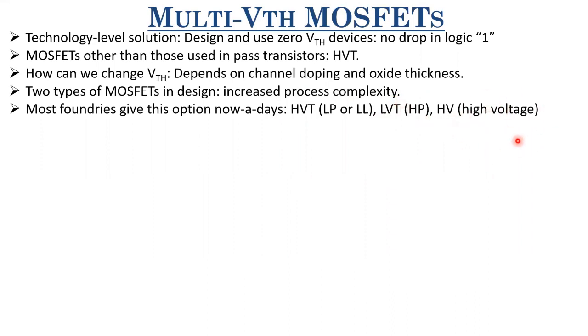And again, there would be some circuits where you need to sustain high voltages. For instance, the NAND flash or the flash memory in your mobile phones, the controller there, or the decoders, column decoders, and so on, use high voltage transistors because these flash devices need a programming voltage in excess of 10 volts. So in your mobile phone itself, for accessing these flash drives, you have to generate a voltage more than 5 volts, which is your battery. So you use a charge pump, and then you use high voltage transistors that can sustain those 10 volts without degrading or breaking down.